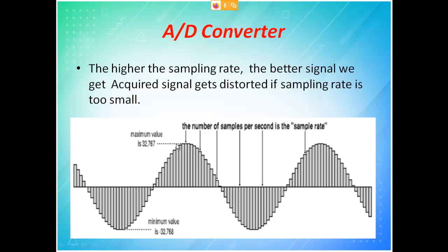So the entire data itself is lost. The input sine is now a triangle for you. So when you want it as a sine itself, you should have more number of steps. More number of steps is nothing but more number of data. Even if the resolution is less, you can go further for higher resolution, that is, more sample rate, or more parts you have to divide this, then only you will represent your sine waveform.